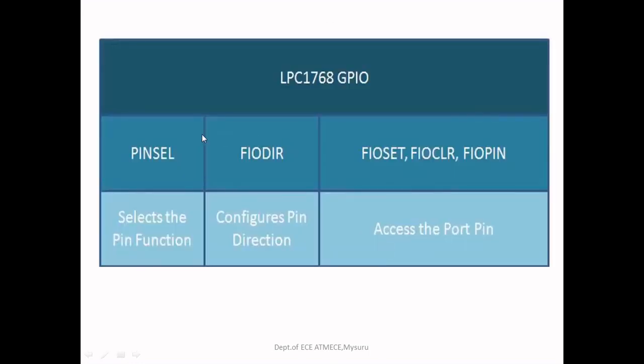So these are all the registers associated with LPC1768 general purpose input output. The registers are the pin selection register, which is used for selecting the pin function, the direction register to configure the direction, and FIOSET, FIOCLR and FIOPIN.